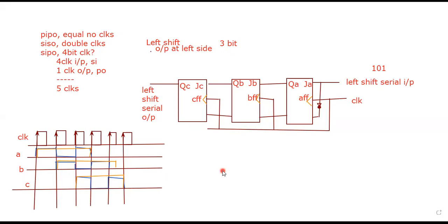In a counter, it may be synchronous or asynchronous, but whatever input we provide, here we have to provide the message bits or input bits as input to the JK FF, and the clock is somewhat different. In a register, we have a common clock among all the flip-flops.